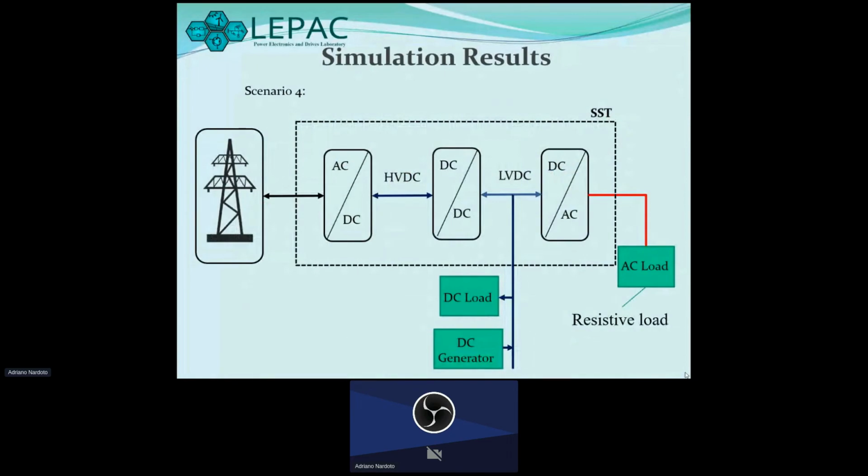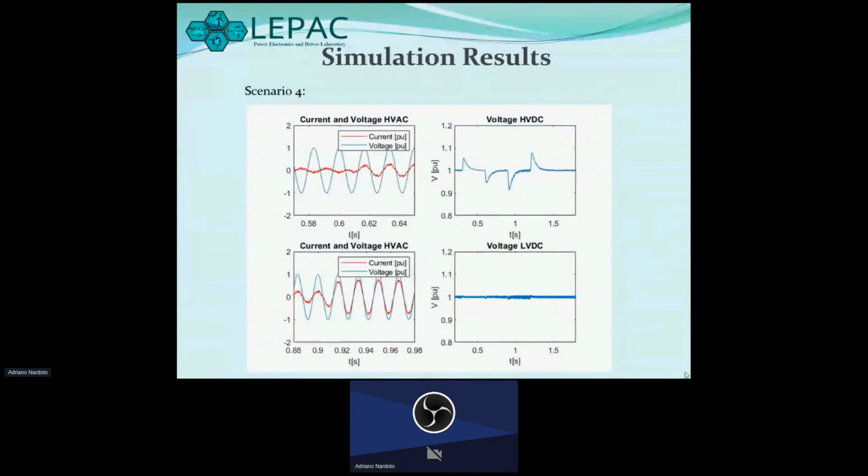Scenario 4. Scenario 4 analyzes the stability of the DC bus in the presence of loads and generators at LVDC. Results for these scenarios demonstrate a small difference in the LVDC bus, which is more affected during scenario 3. Both scenarios show voltage oscillation inferior to 10%.